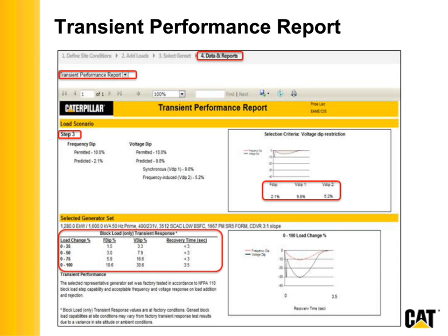And again, it's at 25% load change increments. When we tested the genset in the factory for transient response, we tested at every 5% load step to better accurately document its transient response. So this is a report of the genset that you selected, of its transient response.